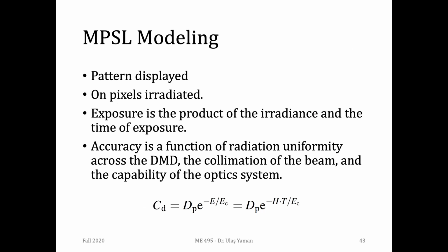Are the energy expenditures similar to the SLA process? Similar, but you need to be using, as I said, a different material. You cannot use the same type of materials we are using in SLA. Since in SLA we are using more power with the help of the laser, but in MPSL, or mass projection stereolithography, we have less power, so your materials should have lower critical exposure values, since we don't use lasers.